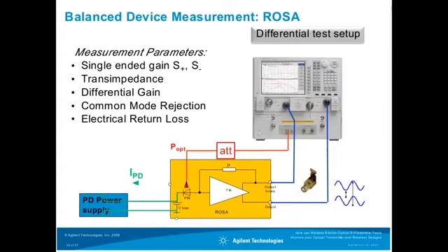For the transimpedance, it's also important that you are able to characterize the photocurrent of the detector, because the photocurrent is an input parameter for the conversion efficiency of the pin diode, and in combination with the feedback resistor, you then can calculate the transimpedance gain of the complete assembly.